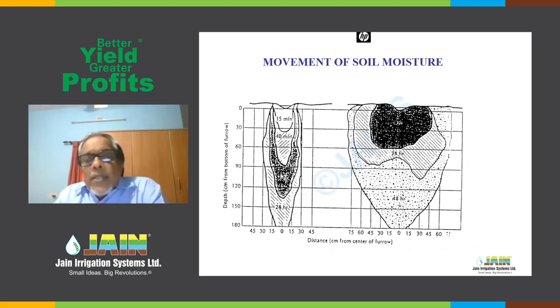But coming to clay soil, it will take a long time for the water to reach 180 centimeter, almost 48 hours. But within the first day, what happens is the water spreads. The water spreads something like 45 centimeter on either side, which is very good.